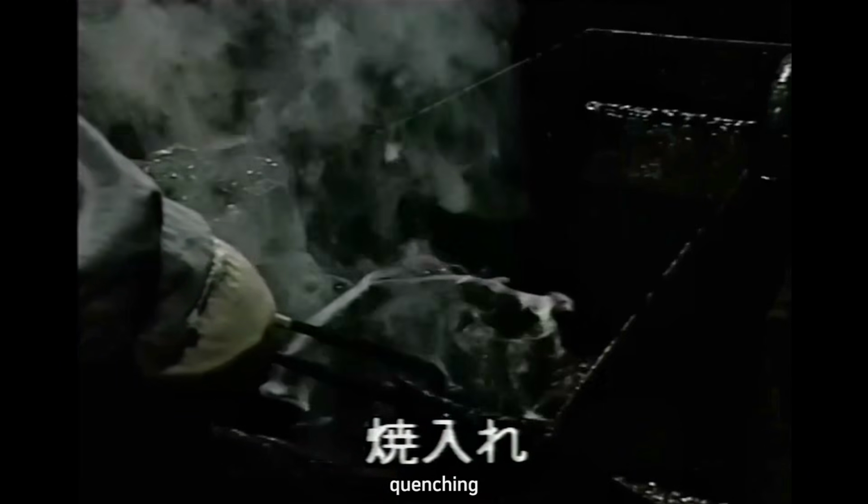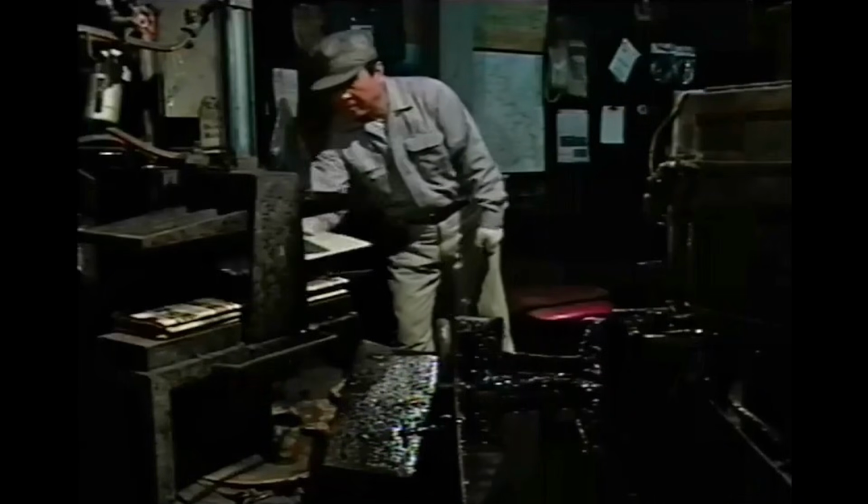Now it is time for hardening. The saw is heated to 800 degrees Celsius and rapidly cooled in oil. Rapeseed oil is used. Pressure is applied to prevent warping caused by the temperature difference.